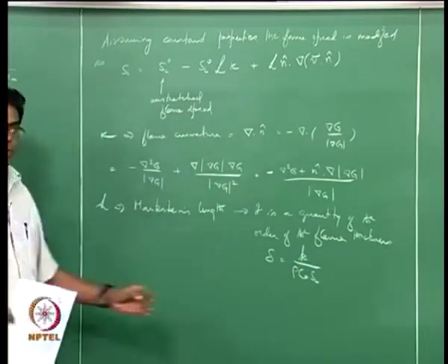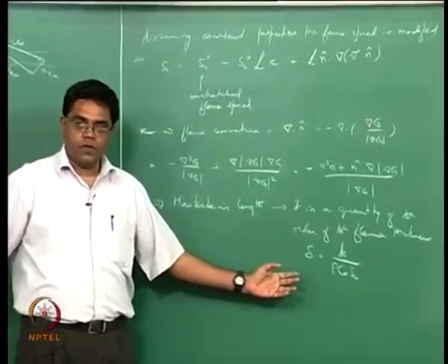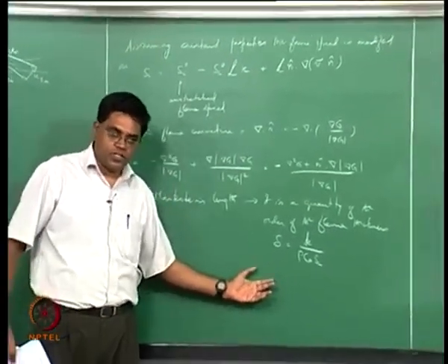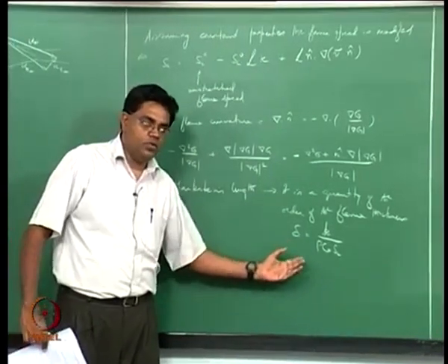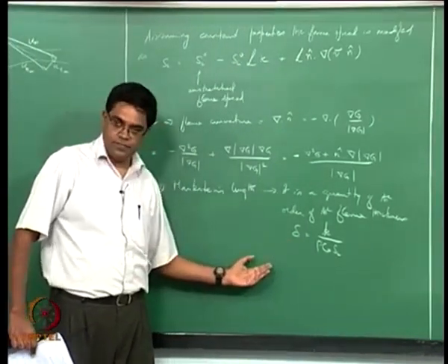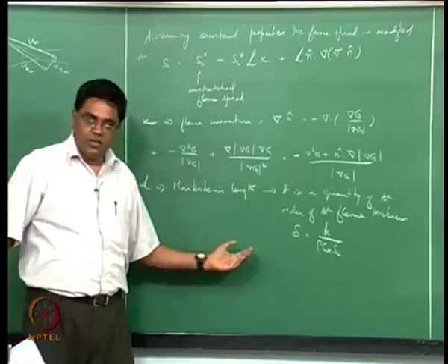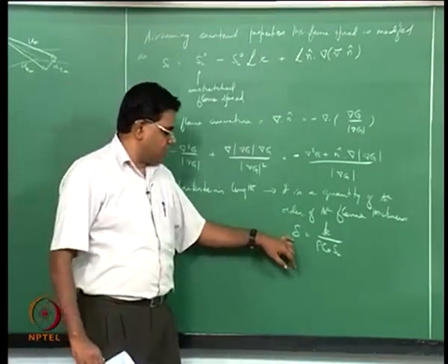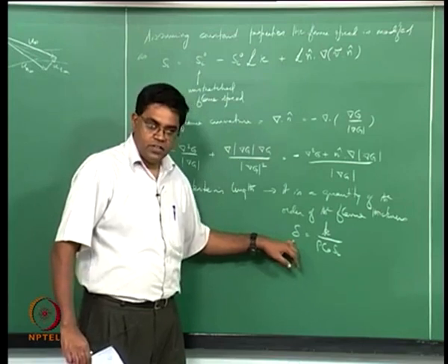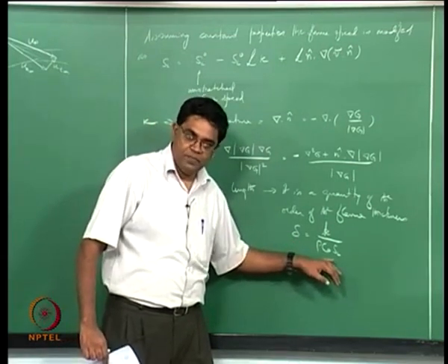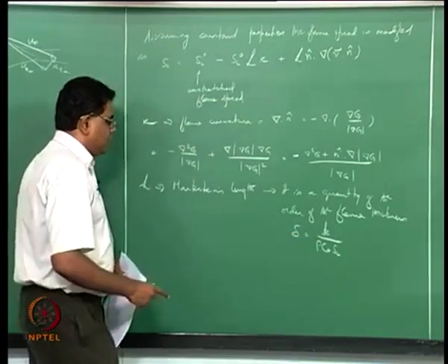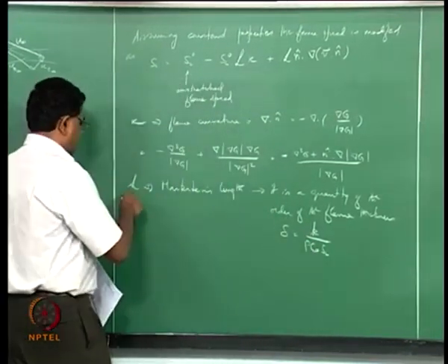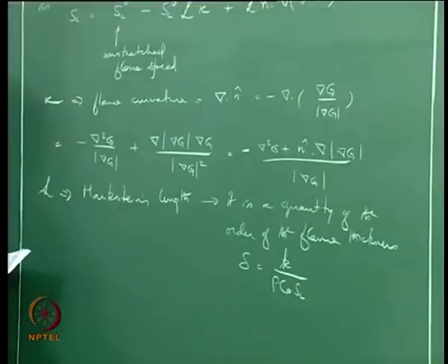This we did long ago, right. So the first time we started talking about the structure of the premix flame, the mass balance in the preheat zone resulted in something like this, okay. But here keep in mind this delta is actually for the stretched flame thickness, the SL is actually the stretched flame speed, okay. And what we are now saying is this depends on L, okay, and